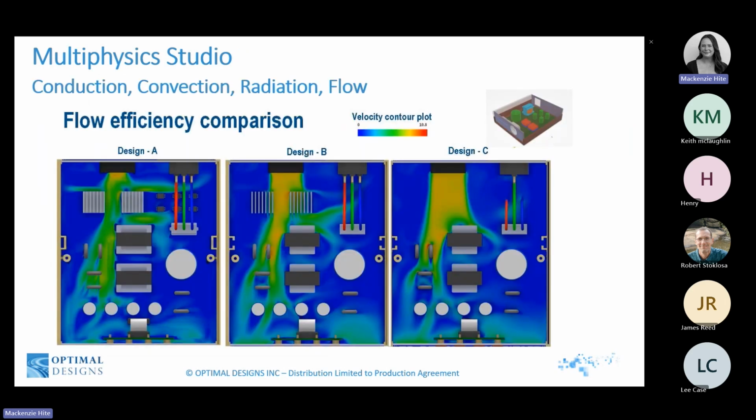The stationary and transient thermal solvers are very quick and accurate, assuming the correct approximation is made for the heat exchange boundary to air. But when a more complicated approach is needed, the conjugate heat transfer solver employs computational fluid dynamics to simulate thermal conduction, convection, and radiation simultaneously in the transient or steady state regime. And it can incorporate fluid flow cooling modules for both air and liquids. In this example, a forced air fan is being used in several configurations for a PCB design.